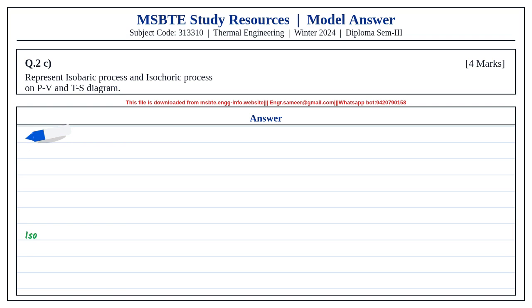Two-stroke engine uses ports for inlet and exhaust, while four-stroke engine uses valves. Power output is higher in two-stroke for the same size, but four-stroke has comparatively lower power output. Fuel consumption is higher in two-stroke and lower in four-stroke.